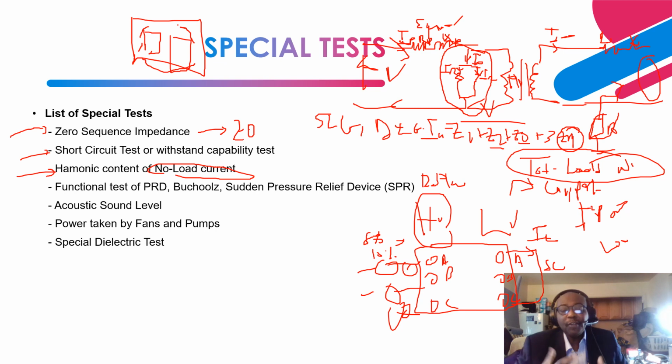So the differential relay will sense it as a fault condition and trip the transformer during energization. Our goal is to prevent such a phenomenon, to help the transformer to ride through the energization surge.